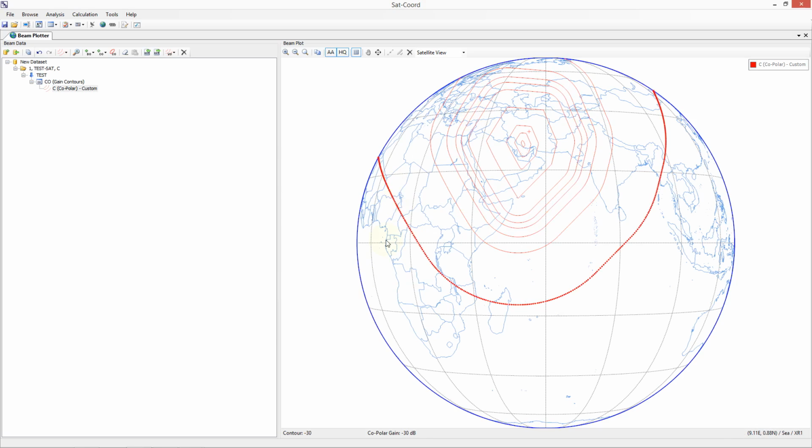You can also see that new contours have been generated both sides of the contour I constructed. I do not want the contours generated inside the contour I constructed, so we can remove those by selecting them and then pressing the Remove button on the toolbar, or by pressing the Delete key. Now I'm finished generating my gain contour diagram. There is a boresight and all of the required contours.